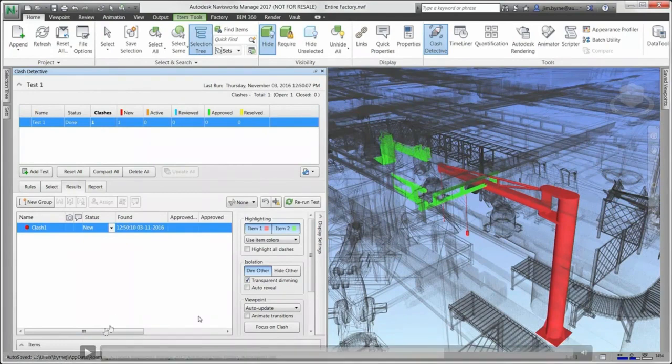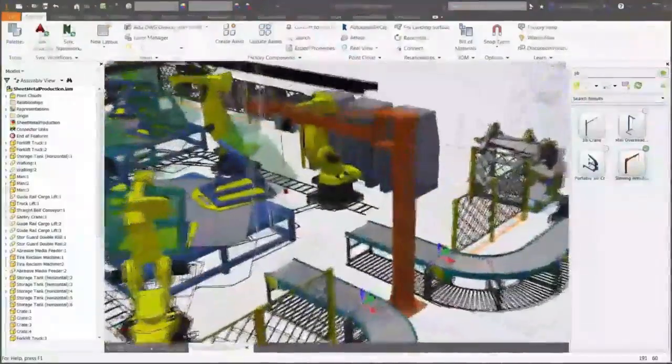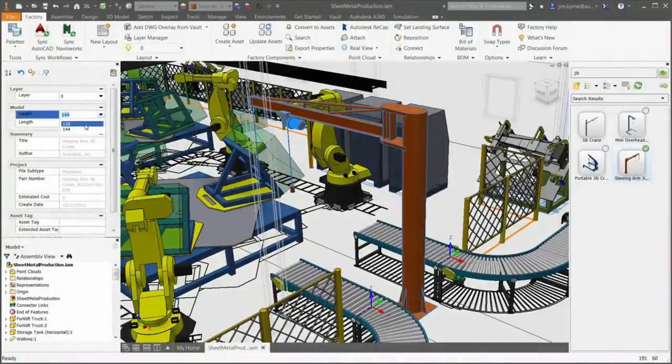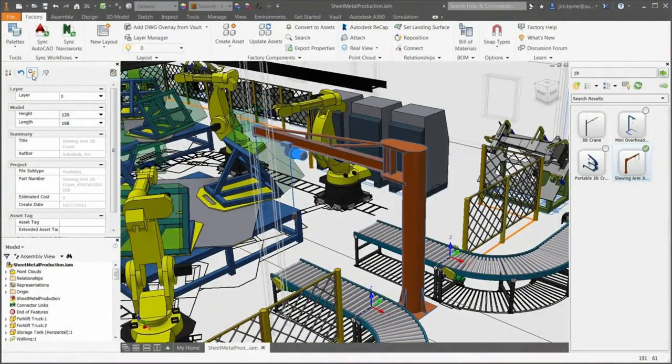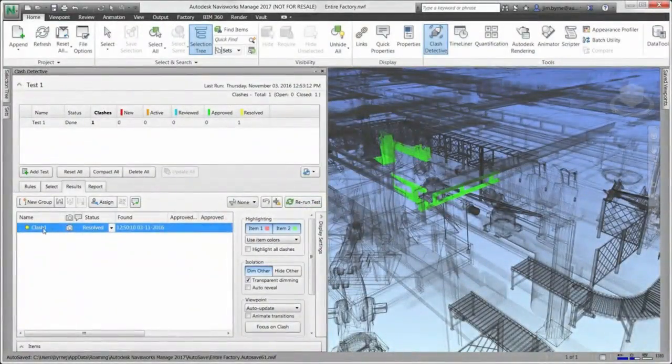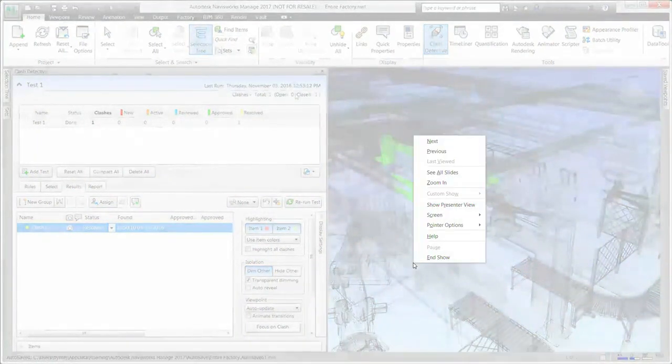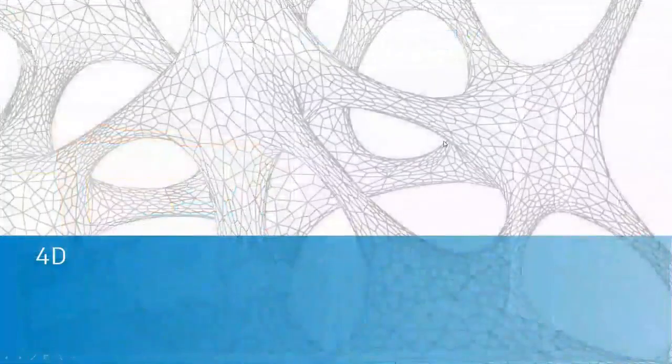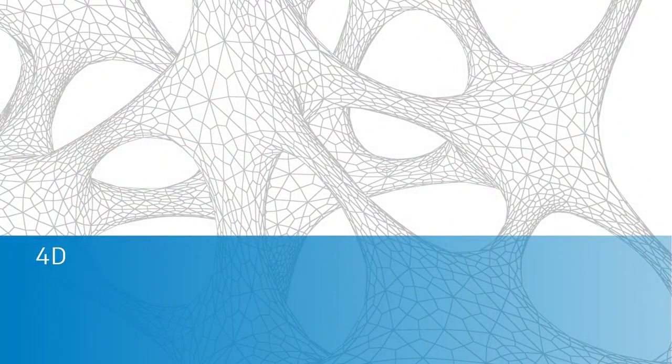Of course, Navisworks is a mock-up, so I don't have the parameters inside Navisworks, but there is a command in Navisworks, SwitchBack, that allows me to go back to the tool, in this case Inventor, change the parameter for the crane, and then go back in Navisworks and check that the collision is solved. I can do this also with the other collisions.